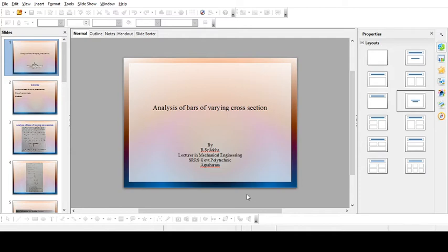So sigma 1 is already given, that is 63.66. L1 means this length we want. For this piece, where the diameter is 40, the length is 2000 minus L. For this we have to consider only this area because this is a hole.